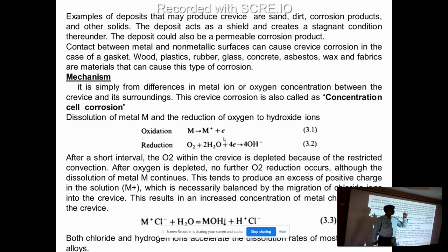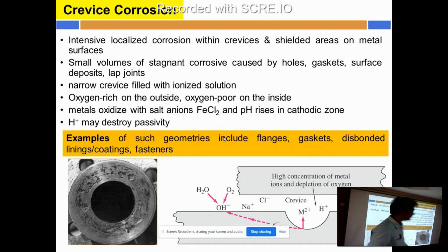Because we have seen zinc in aerated and zinc in non-aerated conditions. Why more corrosion in zinc in aerated conditions? Because in aeration, oxygen molecules are also there, which will try to pull the electrons. Oxygen is also a good oxidizing agent. We have discussed a lot of things. So whenever oxygen and water molecules are there, they try to take the electrons quickly on the surface to form OH minus.